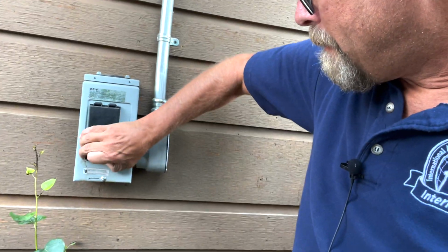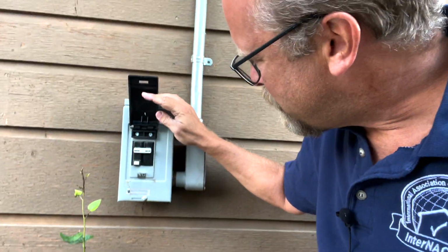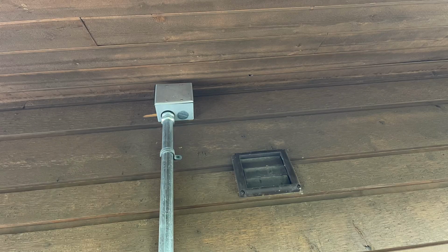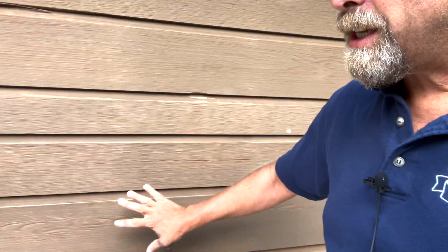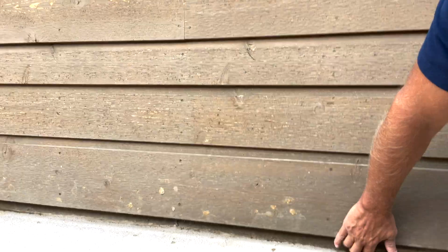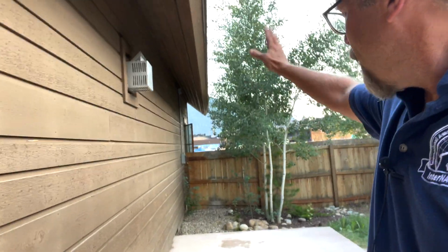So let's see here. Yep, 50 amp GFCI protection. So maybe it's something else, not an air conditioner unit, but maybe a sauna or a hot tub. So I'm taking a look at the siding now. The clearance from the bottom of the siding feels like that's the concrete foundation there. And there's a couple inches. So that's good. I'm really concerned about how flat this seems to be, this surface area, without any gutters.